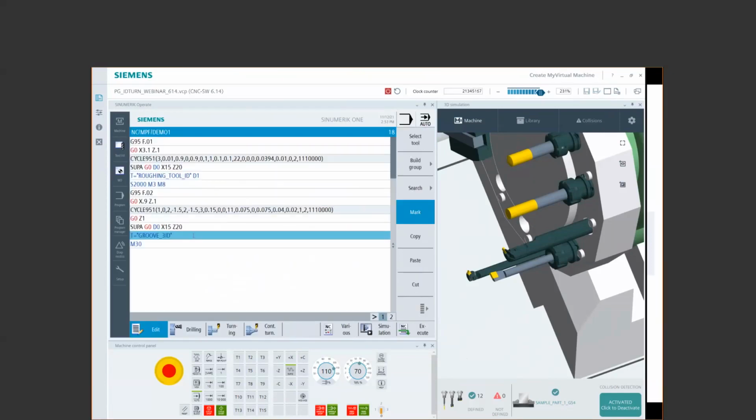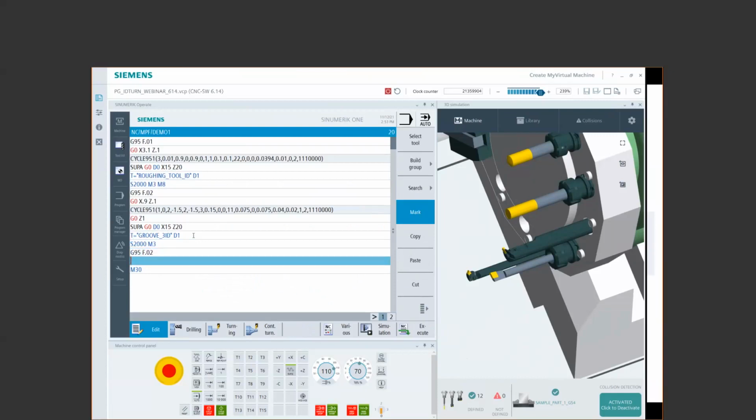So we got our grooving tool in. I'm not going to be very creative for speeds and feeds today. I'm just going to keep using the same, just so you kind of see it. Oh, I want to pre-position. Now in this case, my pre-position is going to be relative to what I've just machined, right? So I just machined a bore that is out to 2-inch diameter.